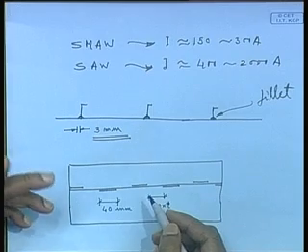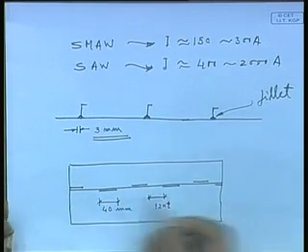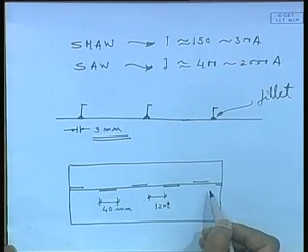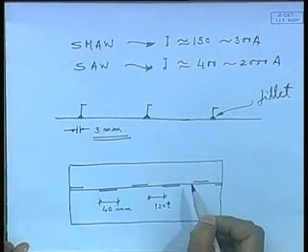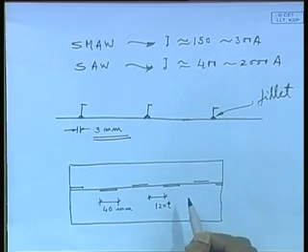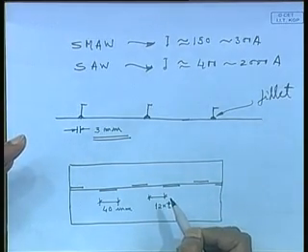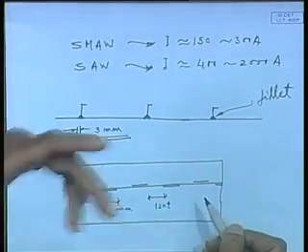So in the process, automatically the amount of heat going into the structure is reduced, because I have not continuously deposited material. I have done some welding, given a gap, again did on the other side, and so on and so forth. This is one of the very effective ways of controlling distortion, but obviously such welding cannot be done for all the stiffeners. In butt welding you cannot do stagger welding when you are putting two plates together. Only in fillet welding, while welding a stiffener, such welding can be done, but it is not always permitted.